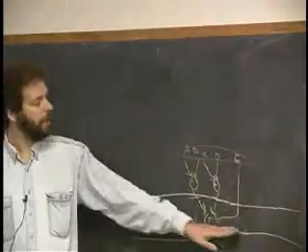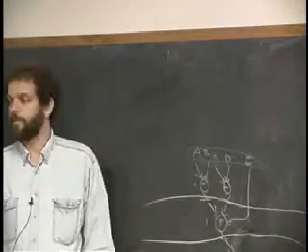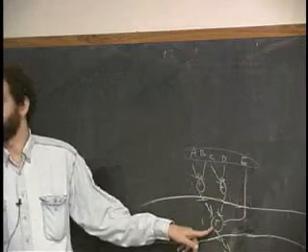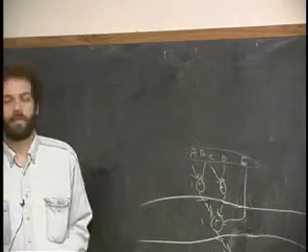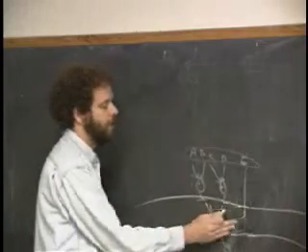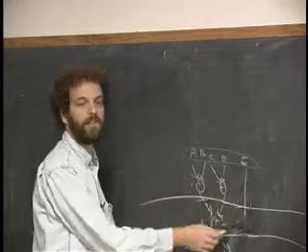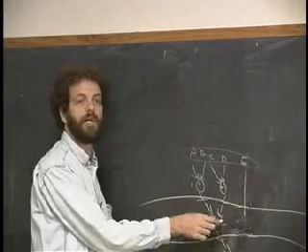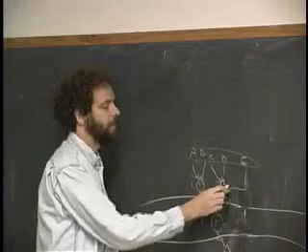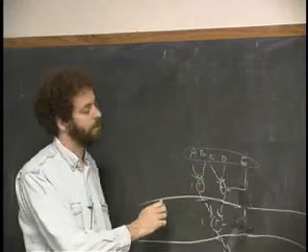That means we need one less register here, but it still takes just as long for the values to get through. Now, unfortunately, this is a 3-input adder. The previous circuit was only two input adders. So if we were constrained to do that, but you see how we would change the number of pipeline stages in E if we did feed it into this level. It would go down by 1. Okay, or we could feed it into here, in which case it wouldn't need to be registered at all. It could just go straight in.